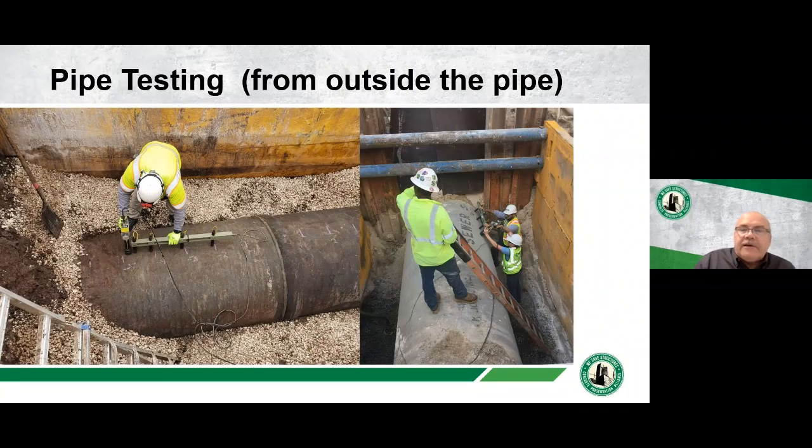But here, looking down with the other ones, we have a relatively shallow excavation. Here, there are some shoring boxes in there. We would want to make sure all excavations are up to the OSHA excavation standards. And we mark out the pipe, and on the left we're at the 12 o'clock position, and we have access to the 1, 2, and 3 and the 11, 10, and 9 over this limited section.